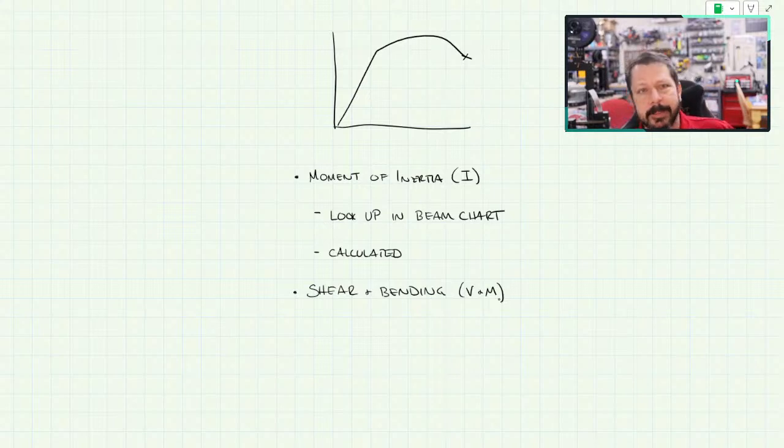You can usually, or actually always, you can tell the correct one based on, oh, if there's a point load here, then the shear diagram should have a step change in it. If there's a concentrated moment, then the moment diagram should have a step change. If there's a distributed load, then there should be this gradual change in the shear, and so forth. So, assuming you know the basic rules, remember we wrote a series of if-then statements for shear and bending. Assuming you know how those work, then you don't have to draw the diagram. You can just identify the correct one, like a multiple choice problem.